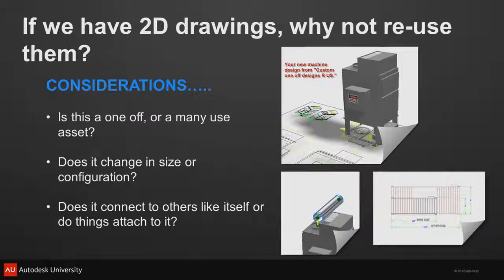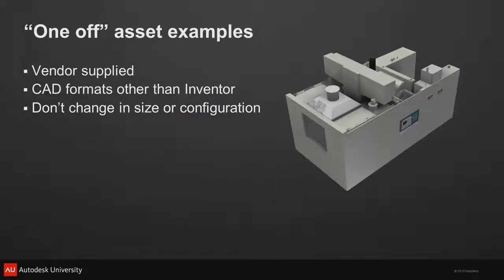Just like when you did your drawings in AutoCAD originally, there was a thought process that you did. It was a little bit different, but basically what you did there is you were considering what layer I should put things on, right? I have to follow my layer standards. I have to make sure that my dimension variables are set and so on. All of those things. So basically, it's not like the worries went away. You just have different ones now. Okay? But they're really not a big deal, and they're easy to work with once you understand where you're going with it.